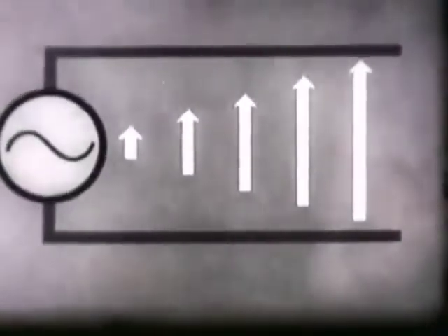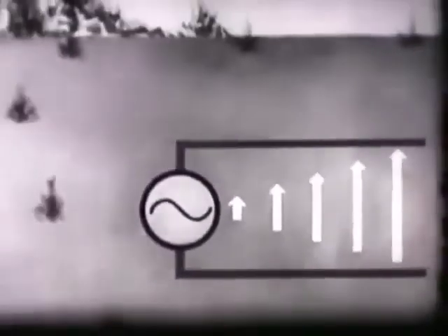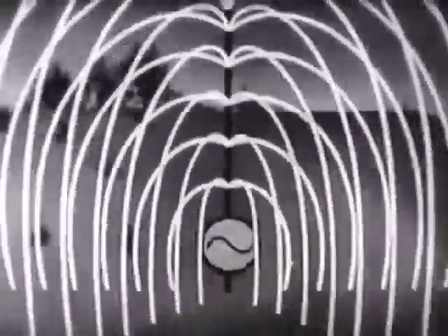What can we do about this? Well, the same quarter-wave transmission line holds a few more tricks up its insulation. When only one wire is moved perpendicular to the other, the closed electric field which existed between the upper and lower conductor becomes a partially open field. Since the lower conductor is grounded, similar electric fields occur all around the upright conductor. Our upright conductor now functions as an antenna, a quarter-wave antenna.